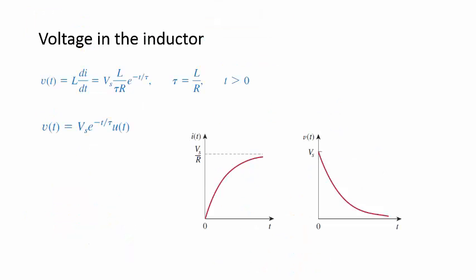We often care about what the voltage is in the circuit rather than the current, and I just wrote current equations, but you can obtain that from the relationship that the voltage is L di/dt, and we have I of t. Your textbook did it for when there were no initial conditions on the inductor, so L di/dt, and I just did that derivative, and the tau moves to the denominator there, and since the time constant is L over R, you end up with that.